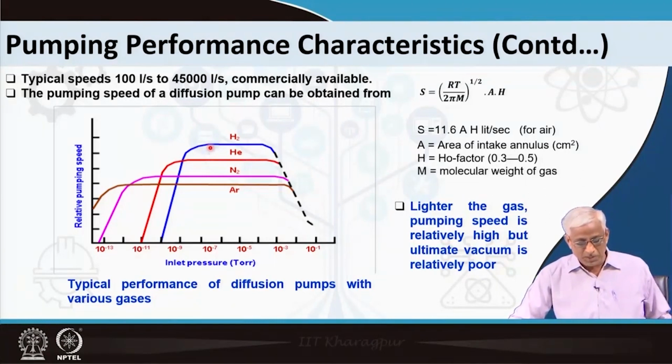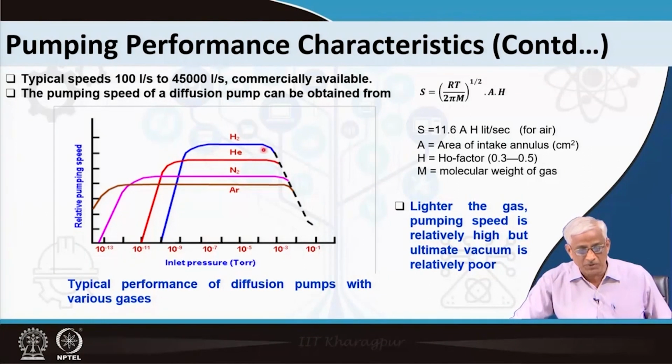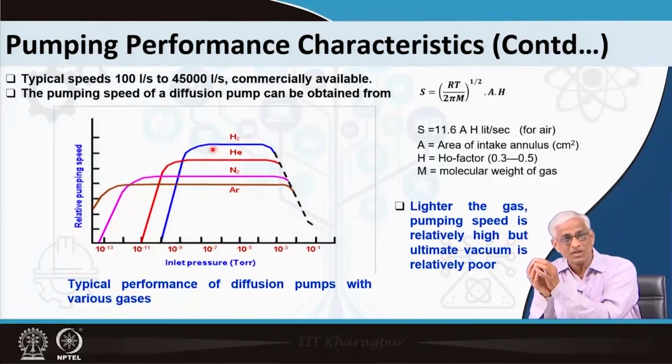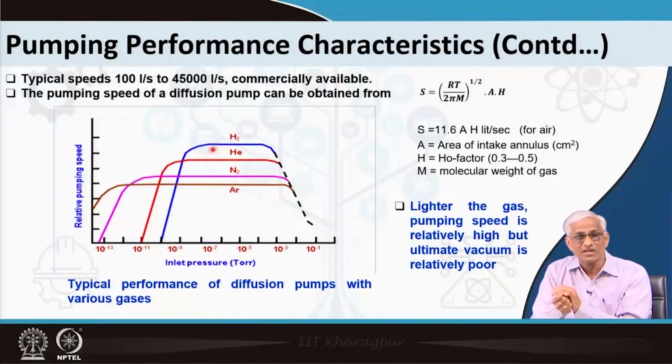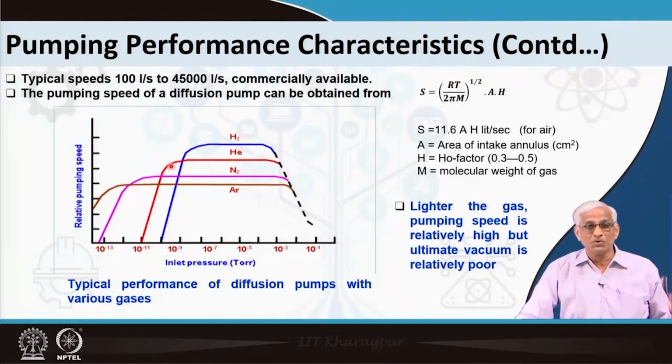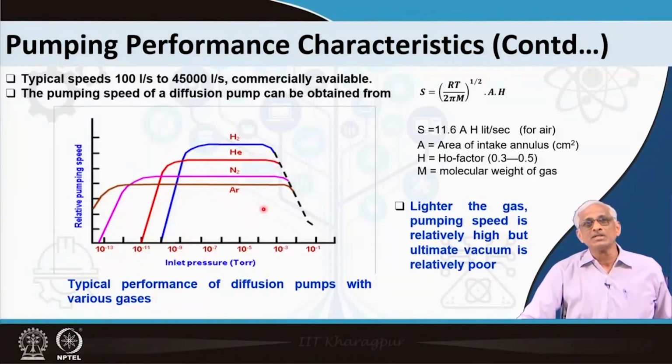Here, the pumping speed multiplied by the pressure is much less compared to this. So the number of molecules it is pumping is much less here, but the pumping speed is constant, because fewer molecules per unit volume at 10 power minus 6 torr is the same as more molecules for the same volume, and when you are talking volumetric units, it will be constant pumping. Okay. So, throughput is conserved again. So, this has been explained.